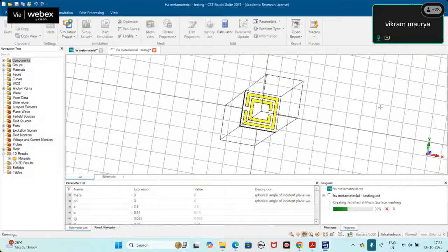with reference to your frequency, you have to select your horn antenna. Which size of horn antenna are you using? I'm using an X-band horn antenna, 18 dBi, the standard one. For that, the distance between your transmitting and receiving antennas, and your structure in between, is also fixed. It is not random. The distance is 2D squared by lambda.